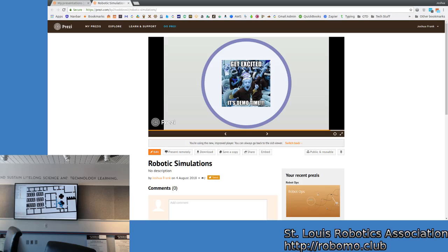Like if I didn't have this map and I wanted to send this robot way over here, it would have no chance. Well, even if you had the map, there are multiple paths to that room. So you could say, I want to go to that room. You'd use an A-star algorithm to do the route, and that's planning. What I'm saying is you come up with the general route through the thing. But then as you're walking, if you get an obstacle or somebody pushes a chair out, you can realize that, navigate around it, and still make your goal be the room.